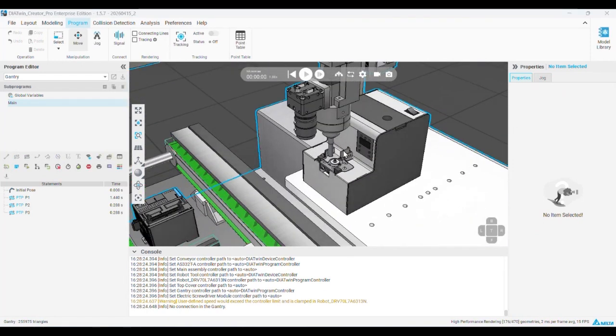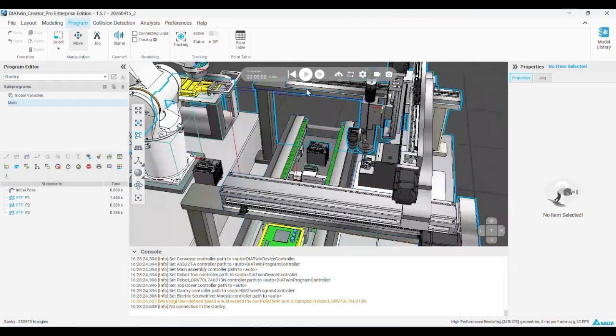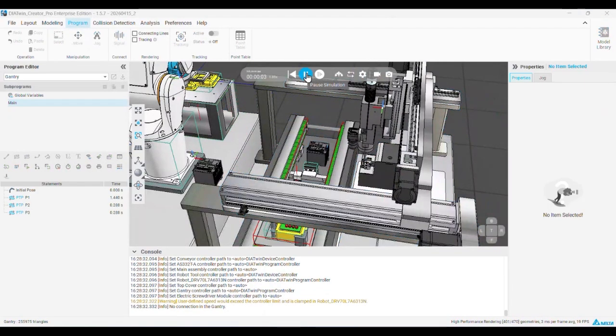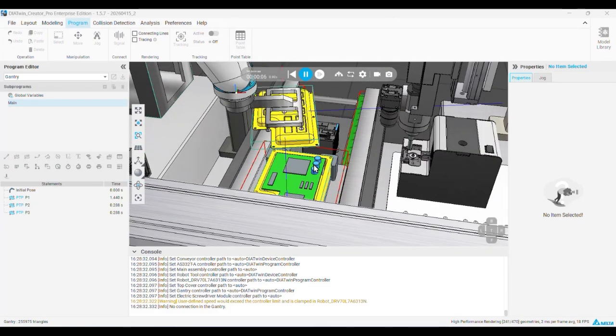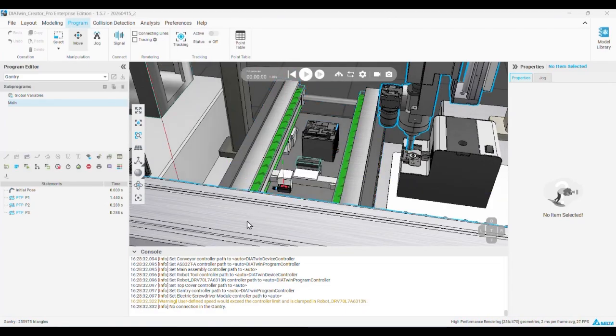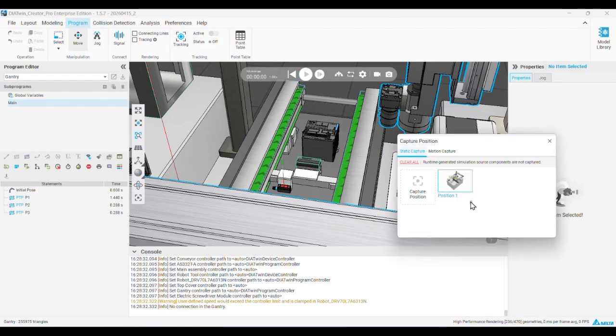So there will be more realistic steps. If you also want to do a screwing process, it's also fine, right? You just need to stay up here and use our capture function to teach the point right here. Actually, it's the same. Maybe I can do a small example for it. I'll use motion capture again.